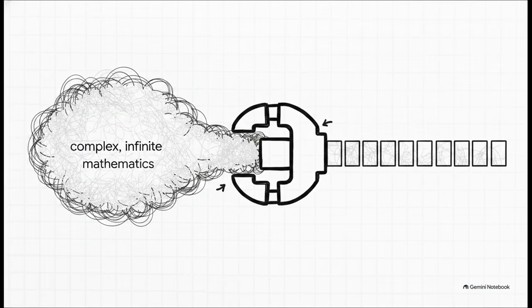So we translate. First, we take our final trained weights and round them off to 2 decimal points. Then, we convert those rounded decimals into binary format using 2's complement. Finally, we lock them into fixed-point arithmetic. For this specific chip, engineers chose a Q3.2 format, meaning every single weight is stored using exactly 6 bits of physical hardware, 1 bit for the sign, 3 bits for the integer, and 2 bits for the fraction. It's the art of squeezing infinite math into physical silicon constraints.